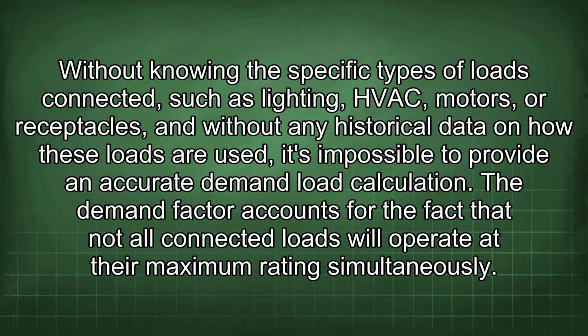Without knowing the specific types of loads connected, such as lighting, HVAC, motors, or receptacles, and without any historical data on how these loads are used, it's impossible to provide an accurate demand load calculation. The demand factor accounts for the fact that not all connected loads will operate at their maximum rating simultaneously.